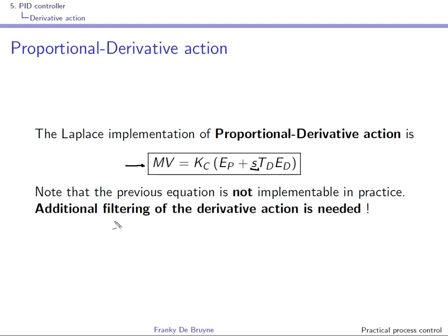So what we'll have to do is add additional filtering of the derivative action to obtain a proportional derivative action that is implementable in practice.